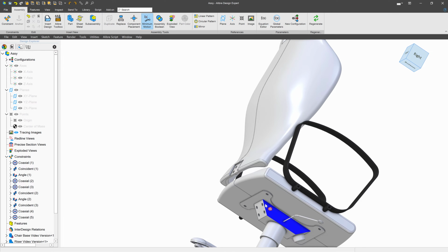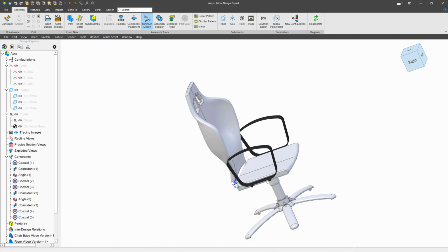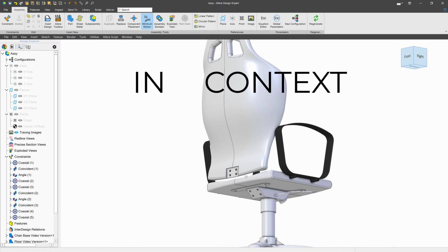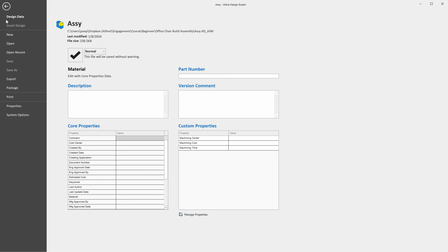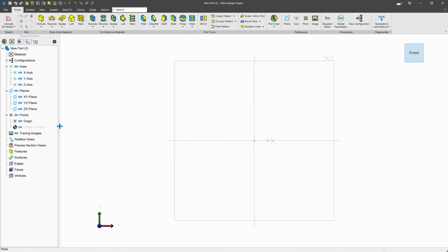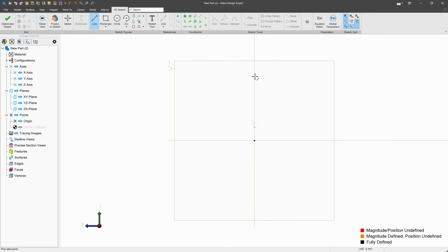So let's make a bracket in this video, but let's do something completely different and make the bracket in what's known as in-context editing. First, I'll start with a new part. And in this environment, I'm going to select my YZ plane, and create a sketch on it. And what I'll do is, in fact, I'll put the origin at the very top, do a vertical line, a horizontal, and then an angular line. I'll set this angular line to have a 135-degree angle.